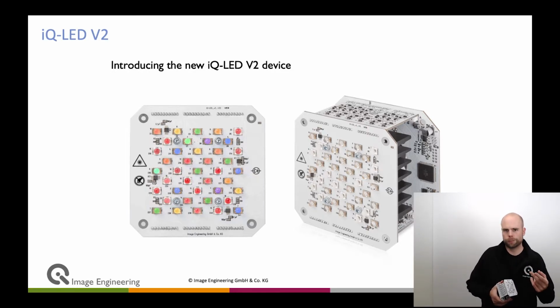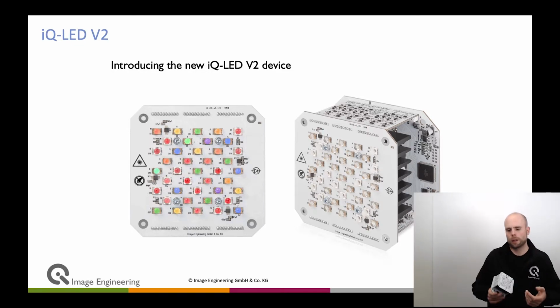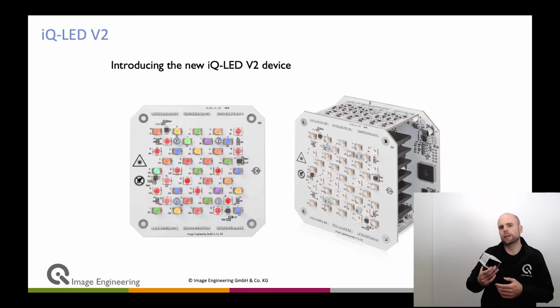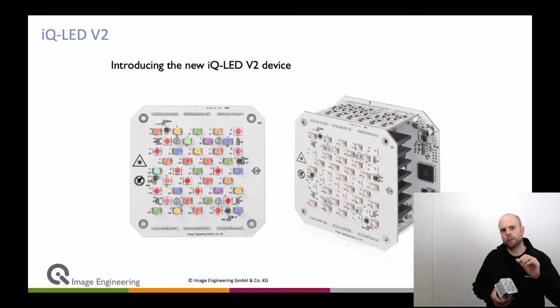On short term, they change depending on temperature. Depending on the temperature of the LED, the emitted light will change. But for that, we have a temperature management system in each iqled module. So we can heat up the LEDs, we can cool them down. So we keep them in a small temperature window. And with that technology, we make them very, very stable. So if you run the system for a minute, an hour, or 5 hours, you have the same spectrum.